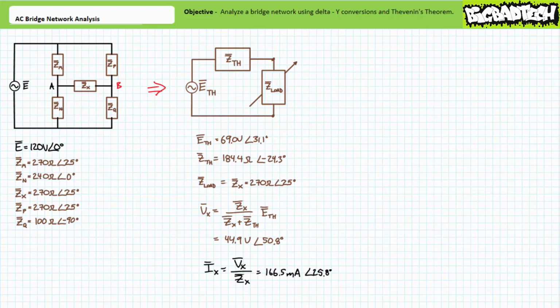In my personal opinion, not only is the Thevenin's theorem a little bit less complicated than the delta to Y conversion, it yields far more usable results. Notably because this Thevenin's equivalent is suitable for the analysis of any load condition, whereas the delta to Y conversion was applicable to one and only one analysis scenario. This being said, both methods yielded the same results.